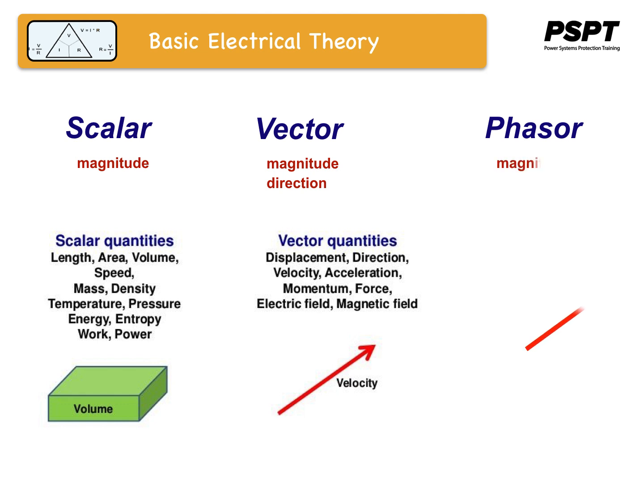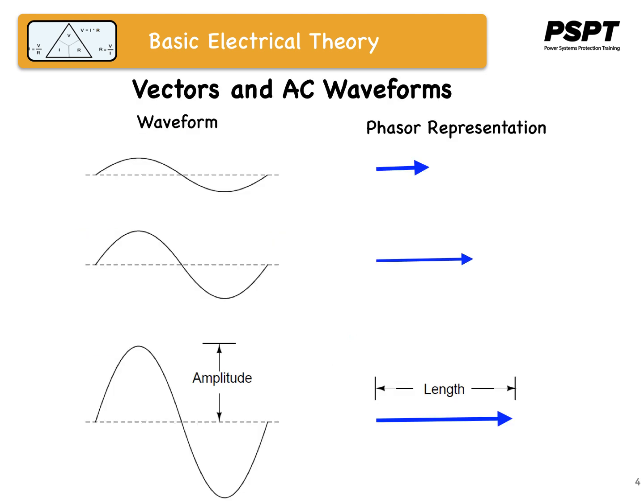Phasors have magnitude. They also have direction like a vector, but they have one more dimension, and that is phase angles, because the phasor is rotating about its tail. When we do the analysis of different phasors, we take a snapshot, or we stop the vector from rotating, and then we look at its phase angle with respect to the horizontal, or at times with respect to other vectors. Okay, so let's build that tool.